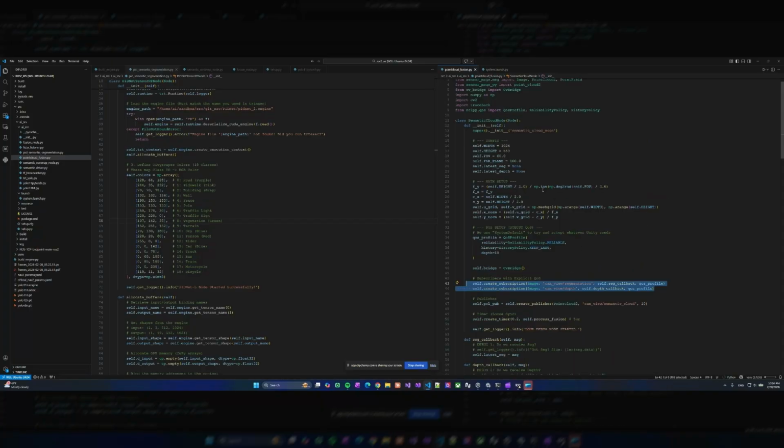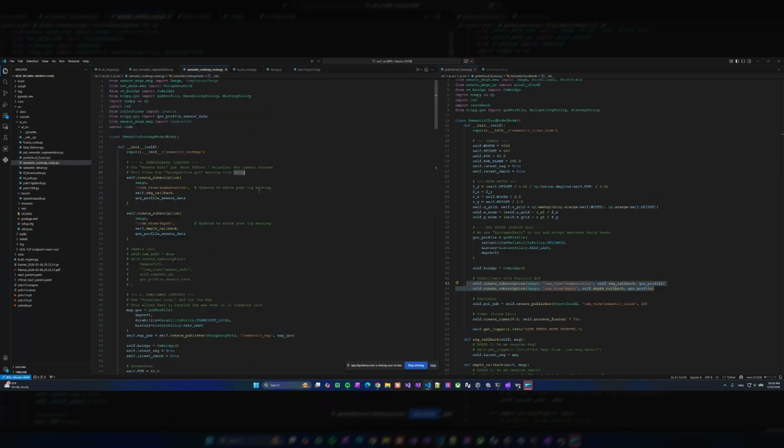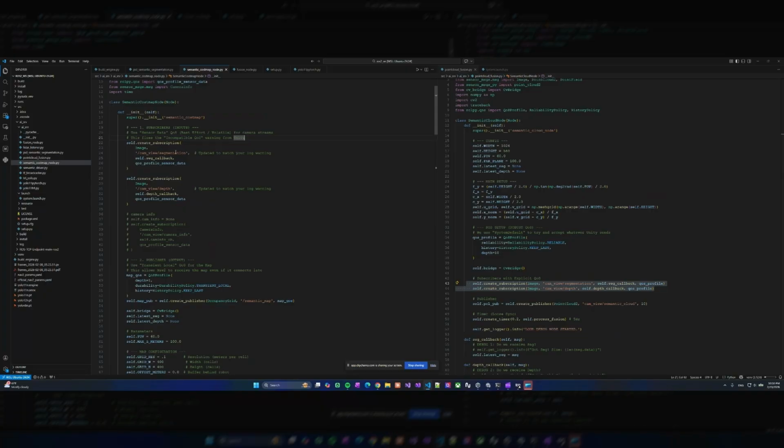Then finally, based on the depth image as well as the segmentation image, we can further convert that into a 2D cost map, and we can use that 2D cost map to do dynamic path planning of the vehicle. So the idea here is that once you have the segmentation of the original picture, we have the color values of each pixel. The purple color belongs to the road, green color belongs to the tree, and things like that. And for each pixel, we have a depth value.